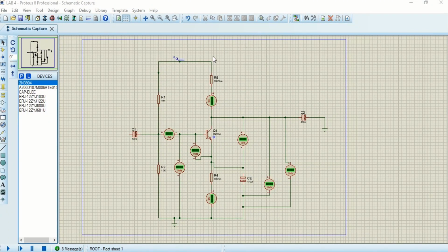Okay, alright. This is part one, the DC analysis of the common emitter amplifier. I constructed this circuit from the lab sheet, following all the pictures from Figure 4. I use a 10 kilo ohm resistor, a 1.2 kilo ohm, and a 68 ohm.